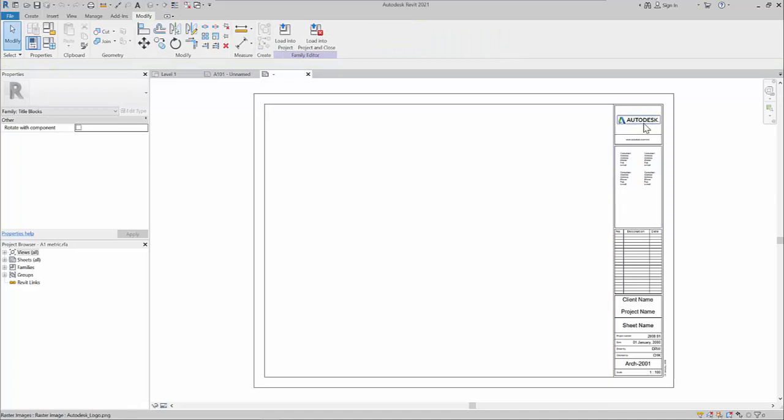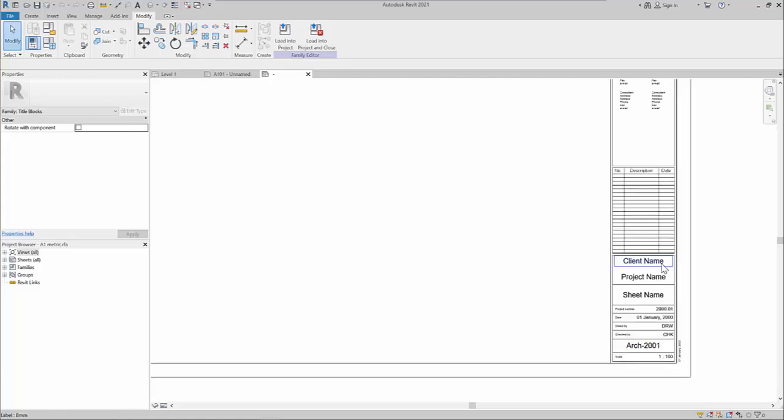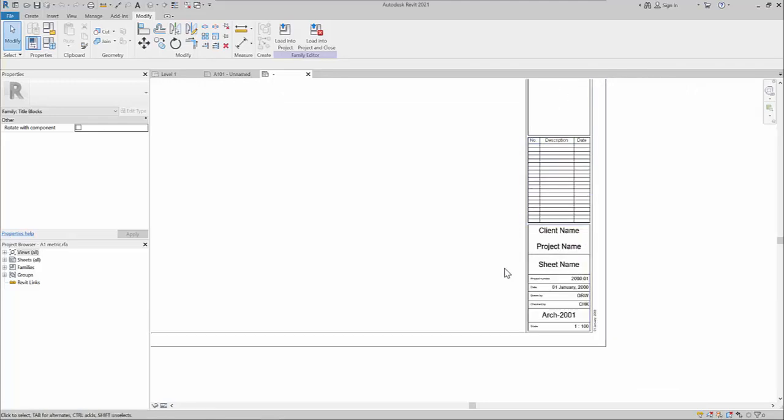So you can see the default title block here. It's got some Autodesk branding and the website and some consultant information. So we're going to look at ways to clean this up and make it customized, make it our own. And again, the key thing for title blocks, specifically on working title blocks, is that this information needs to always be in the bottom right-hand corner of the sheet. That way, when your projects are folded up or rolled up, this information should always be visible.